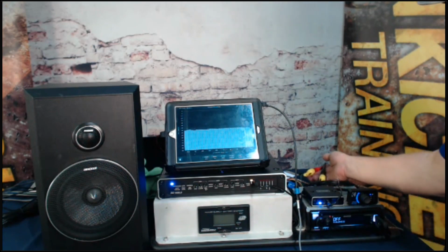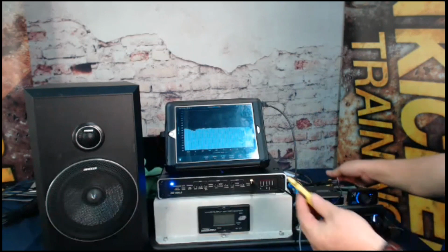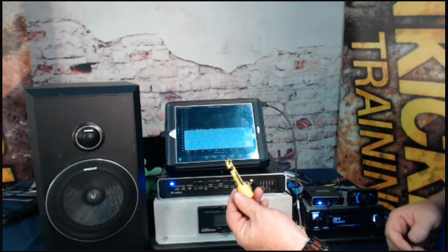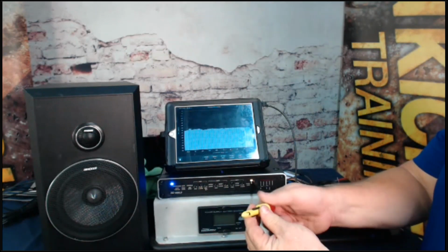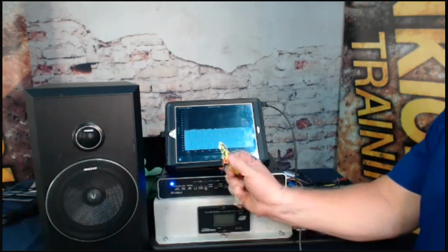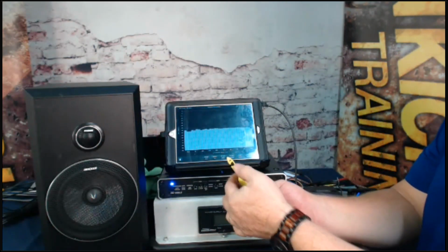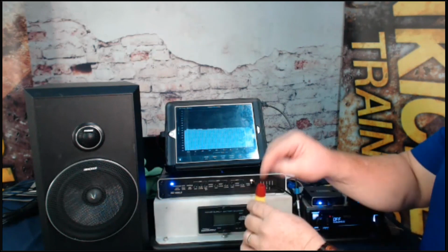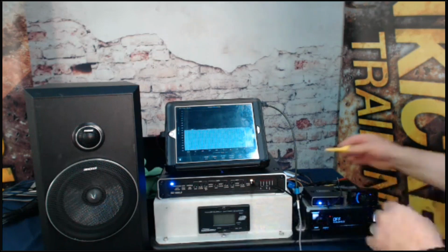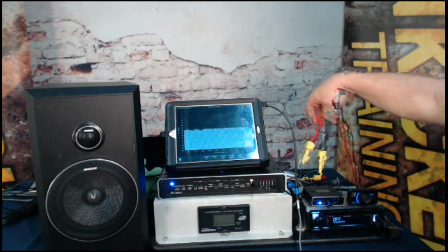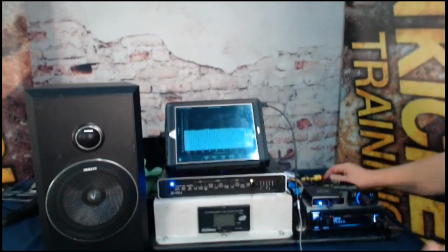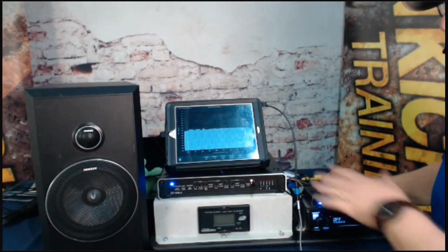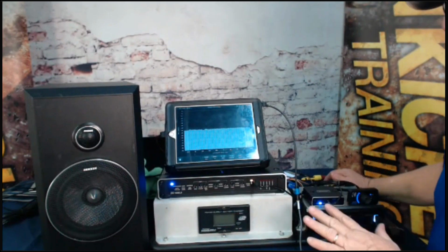Something you may have noticed on the back of the radio, tapped into the speaker leads, I've got one of these, which makes it very easy. It allows you to clip this over a wire, screw the pin in, and that pierces the wire without having to cut into it. Then you plug your test probe into the end, and it makes a very simple, easy contact. So now we know our head unit has a flat source and a flat output, we're dialed in.